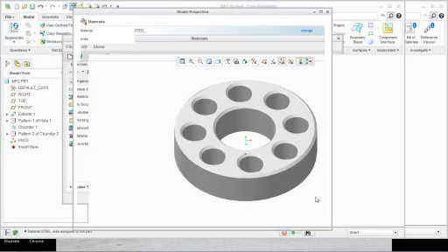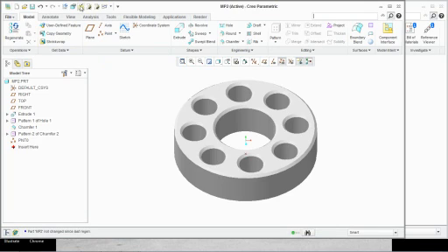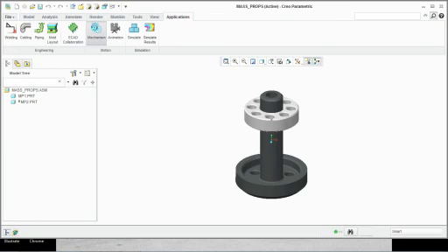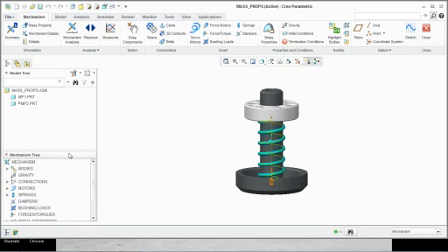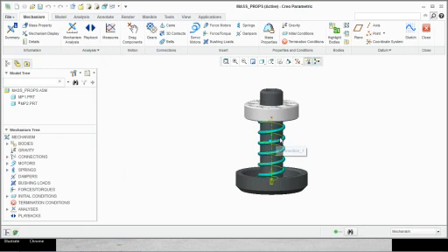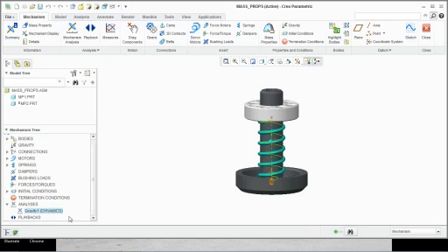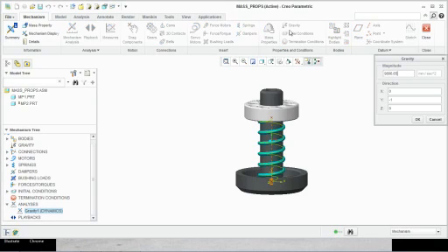And let's get into mechanism. So note that here I have a spring already created, and I'll show you how I created the spring using a different example. So as of now, let's assume that there is a spring right here, and then I'm going to try and run an analysis. So here I have a dynamic analysis. Also notice that I've enabled gravity. There's your gravity.